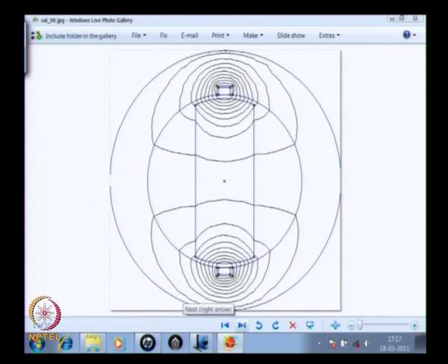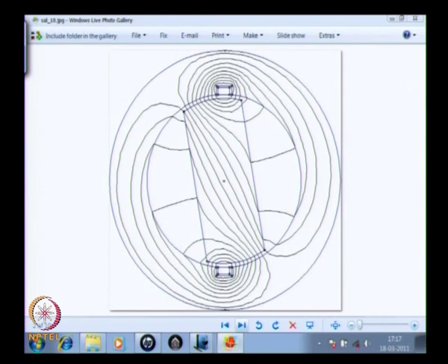Now let the rotor move. So you come to the next position, the rotor has rotated a little anti-clockwise, and you see that again under the pole face there is a rather high flux density distribution, but now it is occurring in this part of the pole face. Below the slot it is a lower flux density, and here the flux density is low and it picks up as you come here. The flux density here is high, here it is high, and as you go around it gradually falls, this region would have a very low flux density.